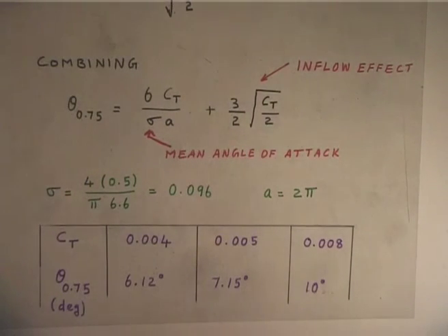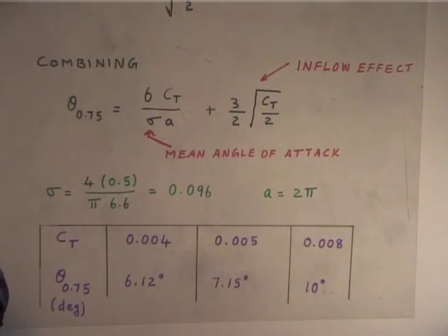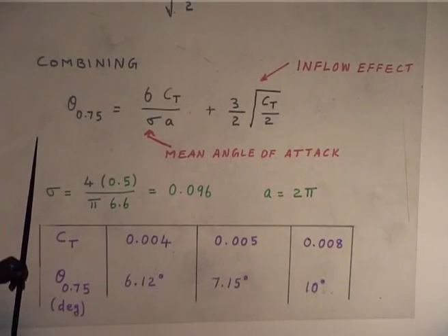When you make it hover, the pilot gives a pitch angle of about 8 to 9 degrees to the blade. You do not go and give 20 degrees or something like that, because in forward flight you have to consider certain time-varying angle, and then you may have stall. So, all these factors come into the picture. We have learned just now very simple hover.